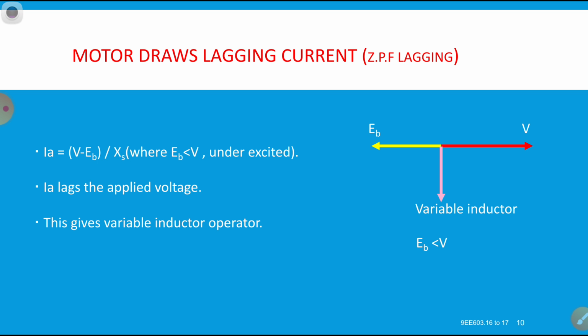Then in this condition, suddenly the load collapses, the load is reduced drastically. Then what to do? We are going to first of all switch off our capacitor banks. Even then, the terminal voltage, the receiving end voltage, is more due to the OLTC tap. Then we are going to reduce the OLTC tap. Then the voltage comes to the normal value. For example, even then in this condition the receiving voltage is more than the sending voltage due to the capacitance of the long transmission lines.